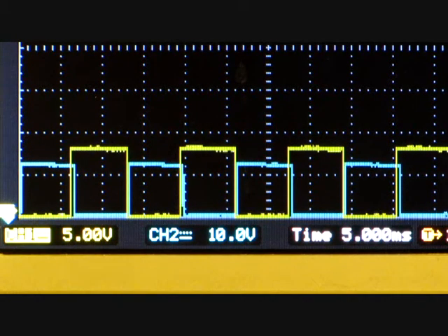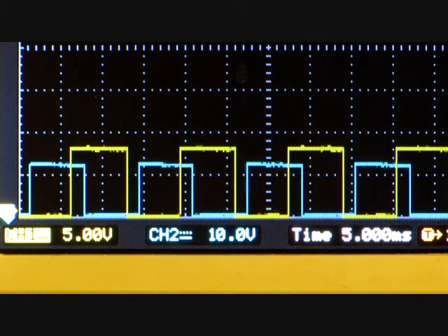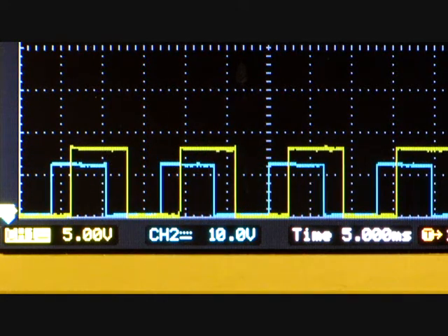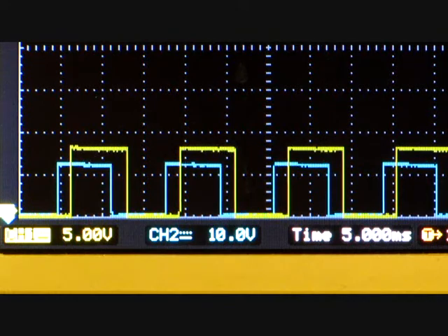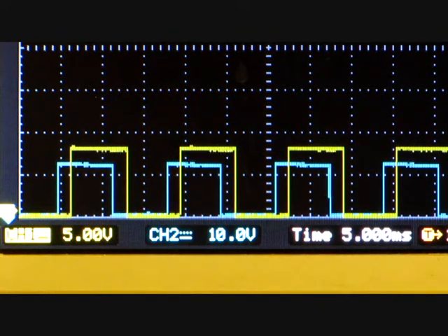Now I can go ahead and turn that off, and the auto delay is set at 0% now. I'm going to manually change the delay, so I'll turn the auto delay off, and it stays centered because it keeps the same percentage that the auto had. Now I can adjust it up or down. I'm going to adjust it up 10%. So I'm at 30% now. You can do that singly or 0.1. You can't really discern the 0.1%, so I'm at 36.6.